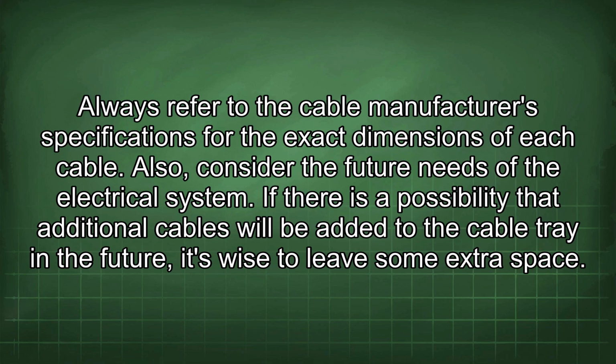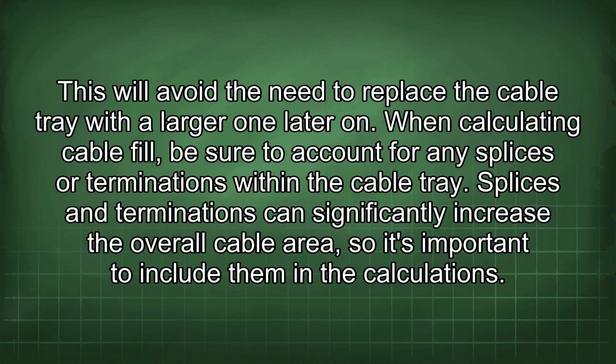Also, consider the future needs of the electrical system. If there is a possibility that additional cables will be added to the cable tray in the future, it's wise to leave some extra space. This will avoid the need to replace the cable tray with a larger one later on.